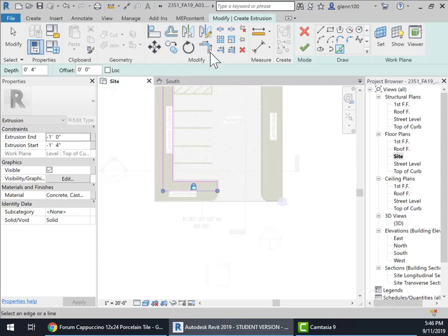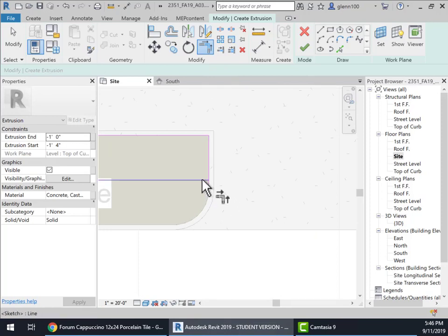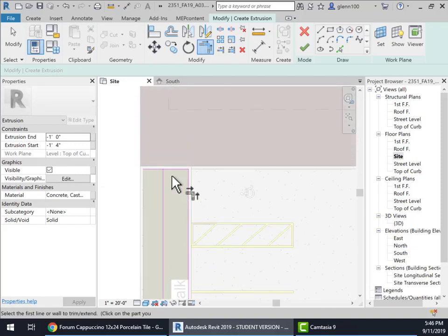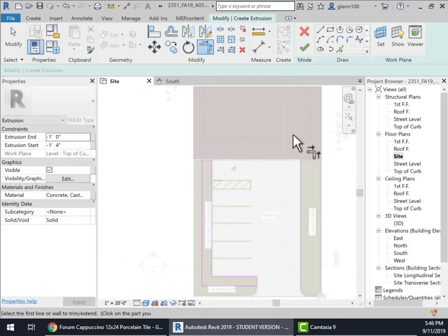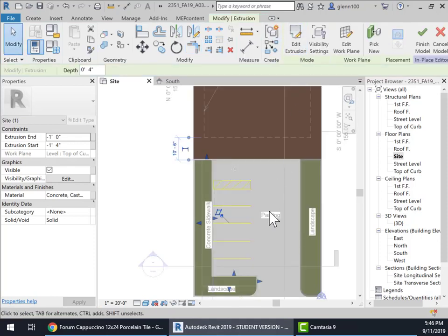And then we've got to make sure they're all trimmed off equal to each other, because you notice right here, these aren't trimmed. So it'll give me an error statement saying you can't close the geometry, and you'll see that this is not trimmed either. These should be. Sometimes I just go through and test it. In other words, trim it anyway, just in case. And so now I've got it all trimmed, and I'm going to say, I think, okay to this.